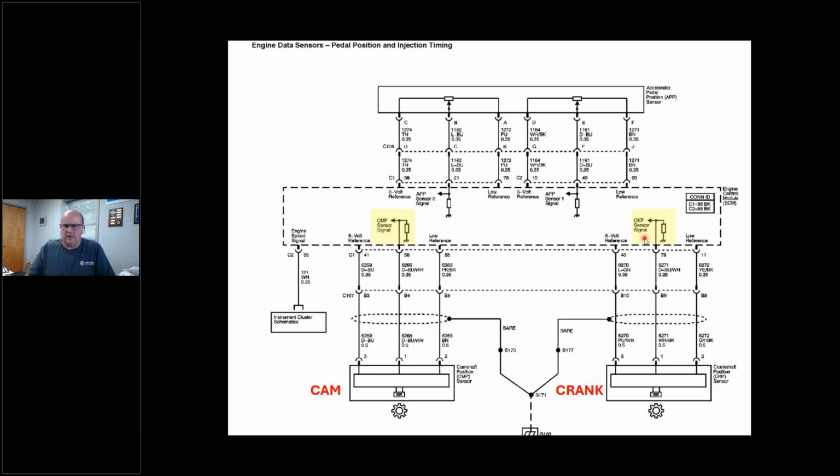that I could work on that N14 Cummins, or I could work on a Detroit Diesel Series 60. We don't do a lot of typical big truck stuff here, but we do a few things. And I can figure out where number 1 fires in relation to a cam signal. So basically what I'm saying is get on a cam signal of anybody's diesel engine and get on an injector pattern. And we're talking electronic diesel here. We're not talking old 5.7, 6.2s, old school diesel. My base of discussion is modern electronically controlled diesels. No 7.3 IDIs, none of that stuff.